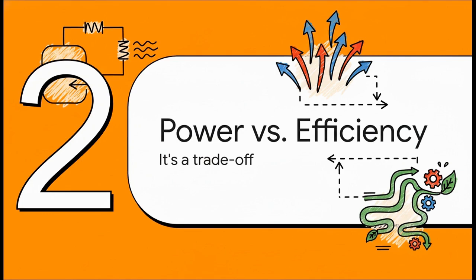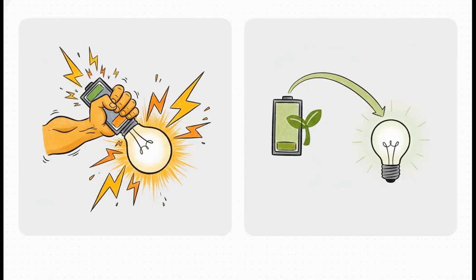This is where we have to untangle the critical difference between maximizing power and maximizing efficiency. They are not the same thing. And this is the absolute key to the whole puzzle. These are two totally different engineering goals. The goal of maximum power transfer is all about squeezing the most absolute watts you can from a given fixed source that you can't change. But the goal of maximum efficiency, that's about wasting as little energy as possible. And to do that, you'd actually want your load resistance to be way, way higher than your source resistance.